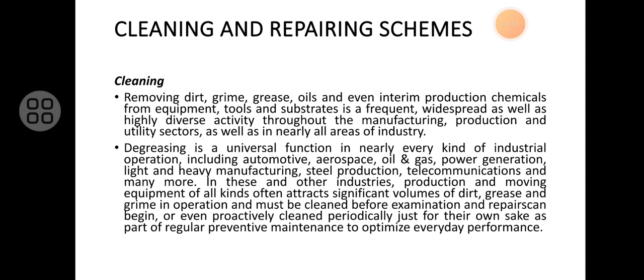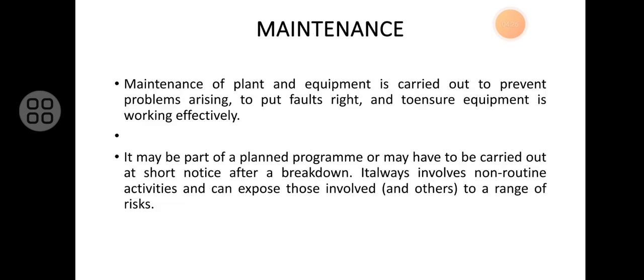Thereby, degreased samples have the highest immediate strength and shear strength. The use of extraction naphtha is also effective in combination with degreasing by rubbing. However, it is not effective when used in combination with immersion, as reflected in the lower strength result.